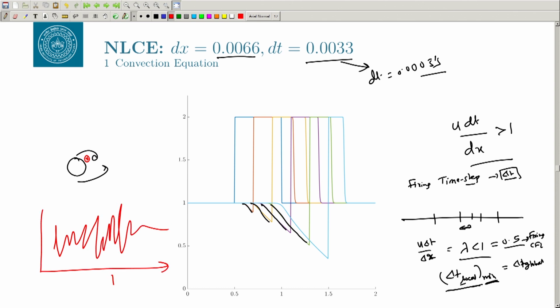So, this is your time and let us say your velocity. And if you want to find out the frequency at which the vortex shedding is happening, you will basically just do an FFT, the fast Fourier transform of this signal, and it will give you the frequency, or you can just measure it also. If delta t is fixed, then you can use this. If delta t is changing, then you cannot use the FFT, right, because your delta t itself is not fixed. So, the 1 by delta t which gives you the frequency is not fixed, because delta t is changing in every time step.